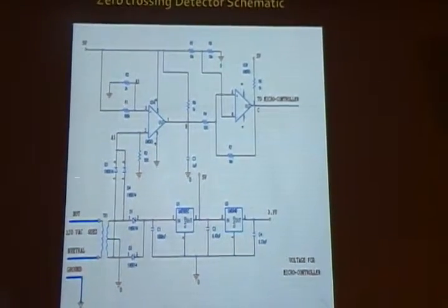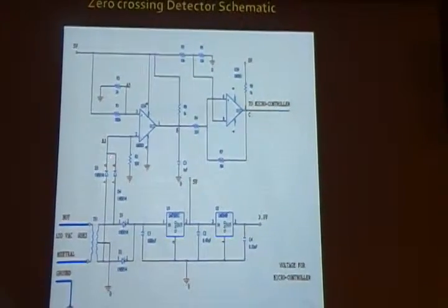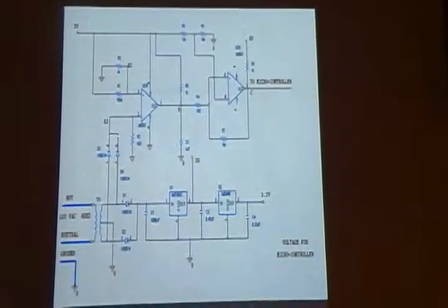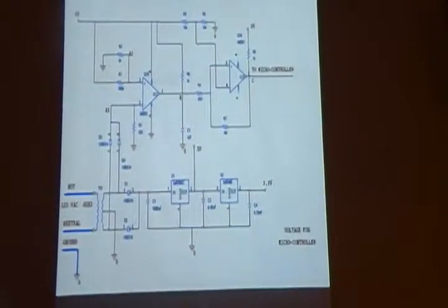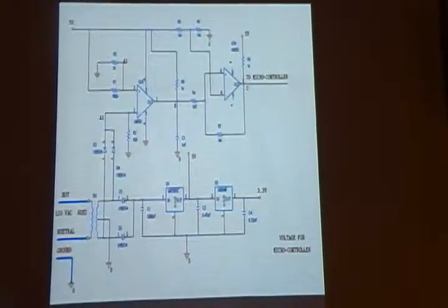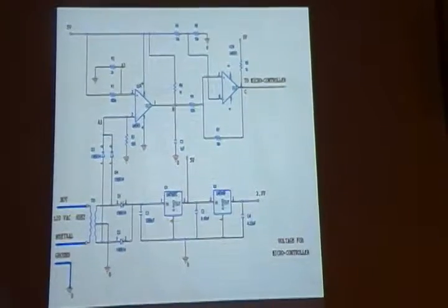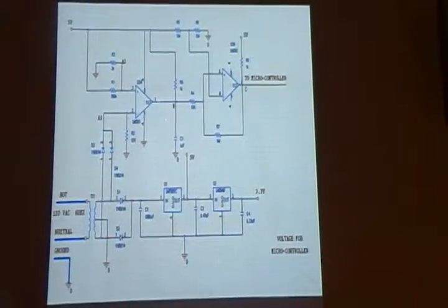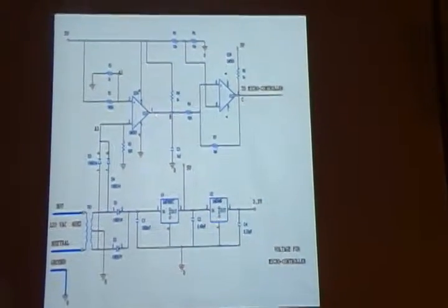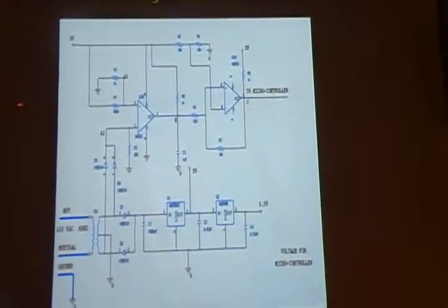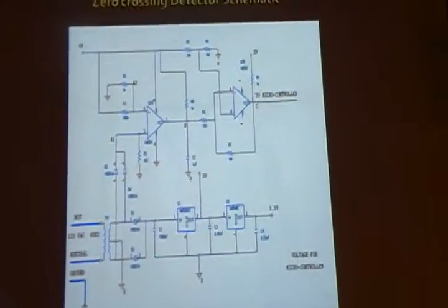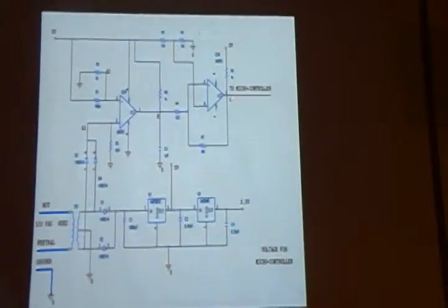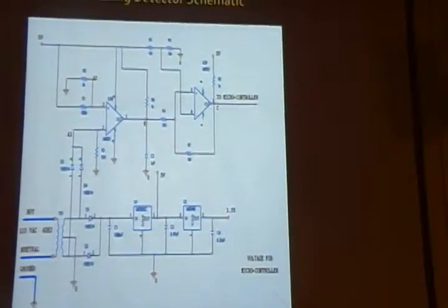The full rectified 6 volt DC is then supplied to an LM393, which is this whole thing. This acts like a comparator. It compares the 6 volts with a very low level voltage close to 0. When the voltage is below that level, a pulse is generated for a very short period of time. Right here, we generate a pulse of a very short width, but it has a curve, it's not sharp enough. So we send it to another block, and the output that we get from the next block is a pulse which is very sharp and steep.